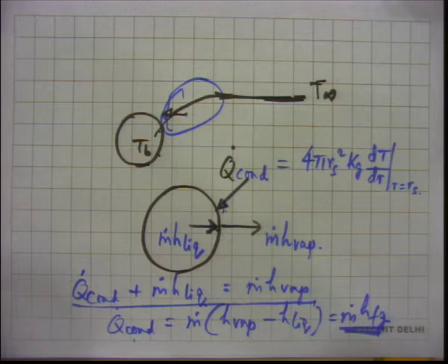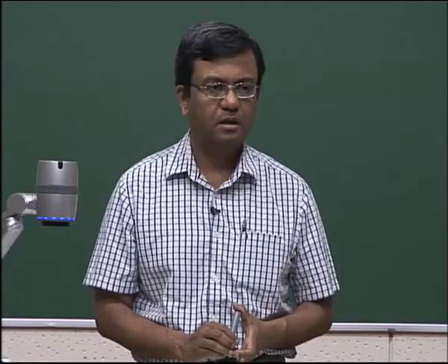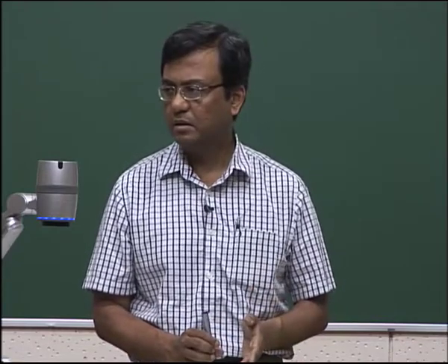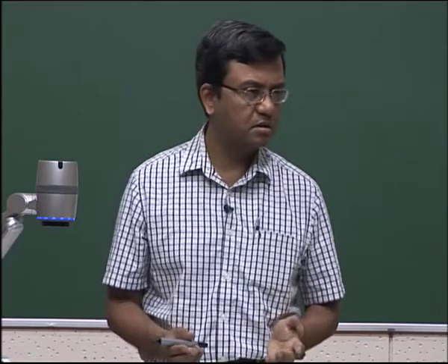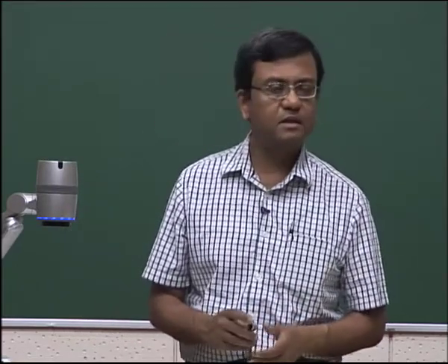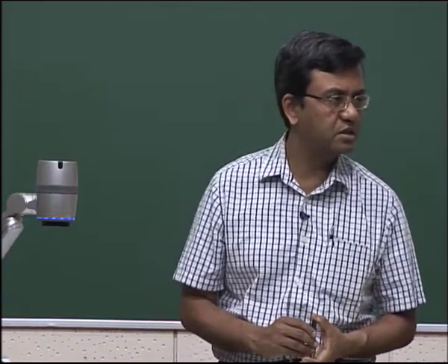We did that yesterday. Now what do we plan to gain out of all this? What is our purpose again? Our purpose is to get m dot. M dot is the mass loss rate, isn't it? It's actually the mass flow rate in the domain. We saw yesterday that this m dot is equal to m dot of fuel, because m dot is constant according to our assumptions. We made a very important assumption yesterday. We said that we are tackling a quasi-steady problem, right?